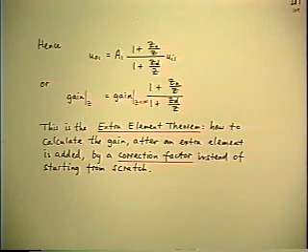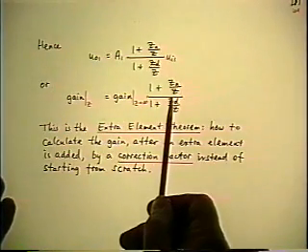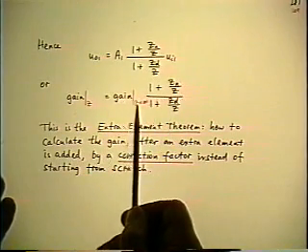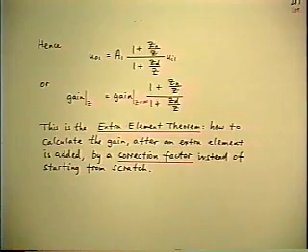And you never calculate anything on the box in the presence of the Z. All you do is substitute into this result, and that gives you the answer, in place of solving the whole system. So that is the extra element theorem.